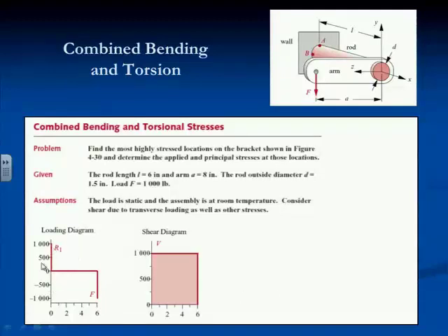So if I integrate this, I'm sorry, there's my force F out at the end. I didn't mention that. So there are the two forces shown. R1 is, of course, equal and opposite direction to F, right? From the sum of the forces equals 0. And if I draw the shear diagram for that beam, I have a value of R1 at the outset, and I see nothing else as I walk across the beam.